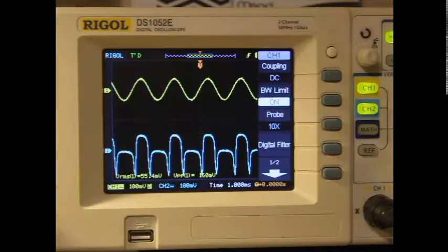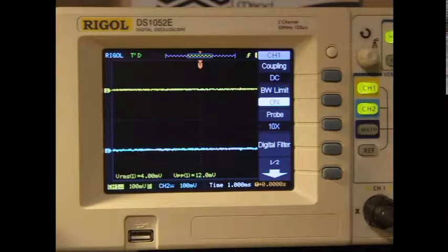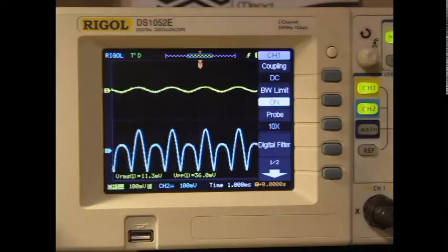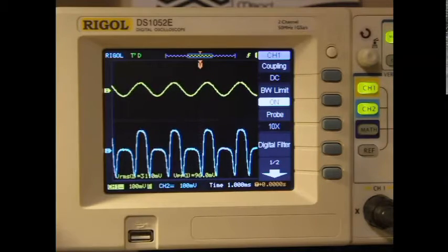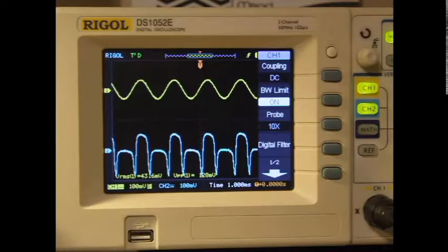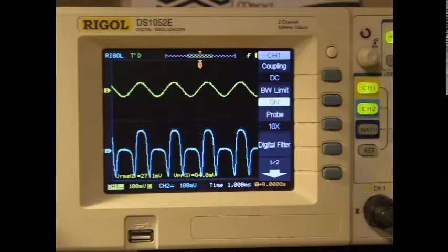I'm going to turn the input down. Actually, let's turn the input all the way down, and then we'll bring it up slowly. What do we see? We see that where we have a sine wave on top, we have kind of a little humpity hump thing on the bottom. That's pretty different. You can see that basically the humpity humps are always going up. The bottom half of the would-be waveform is, instead of going down, flipped up.